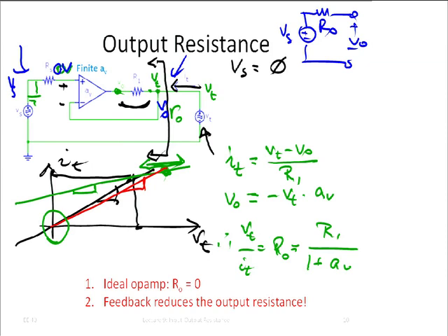But now if I see that the simulation gives a totally different result than my analysis, then first maybe I stick in an operational amplifier that has a much higher gain. Okay, and then if there is agreement, then I know that the problem is the finite gain of the amplifier. If there is still not agreement, then I know the problem is that I've made an error in either my calculations or I put the circuit wrong into SPICE.